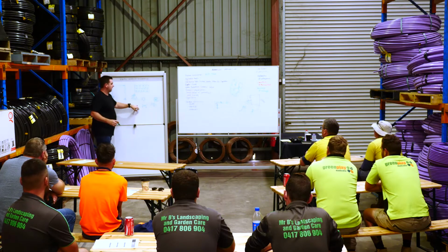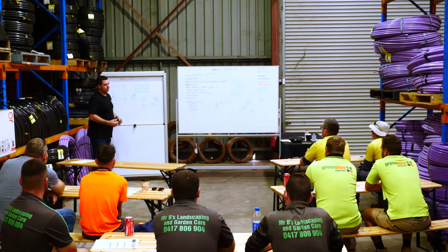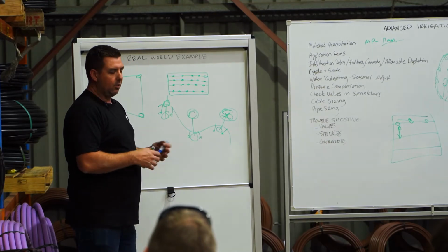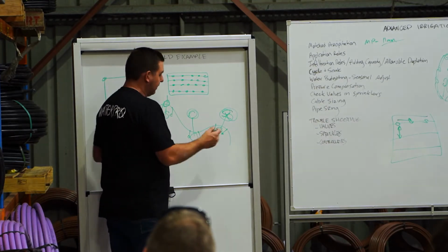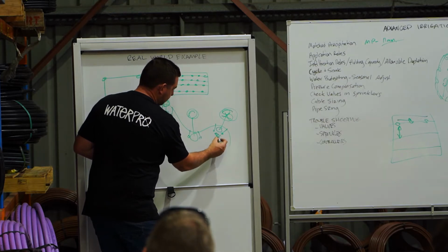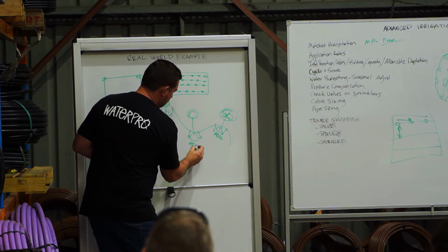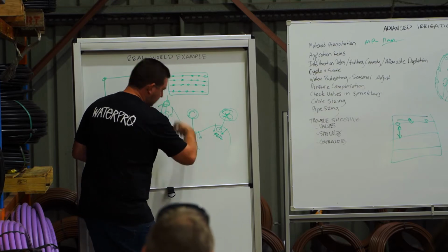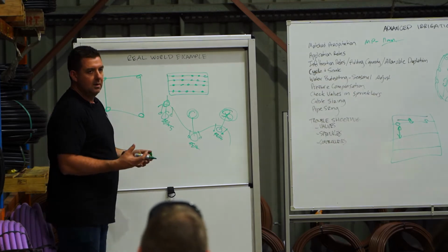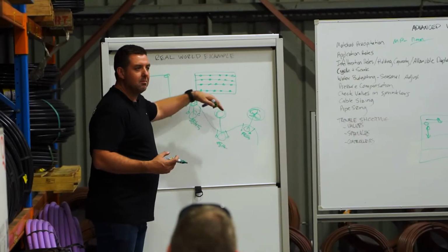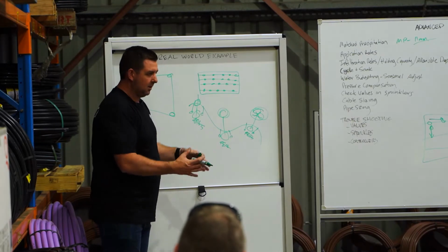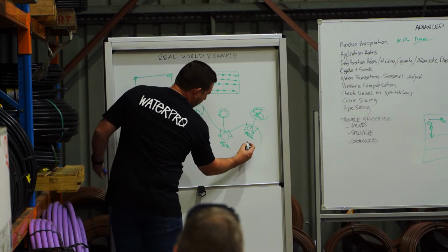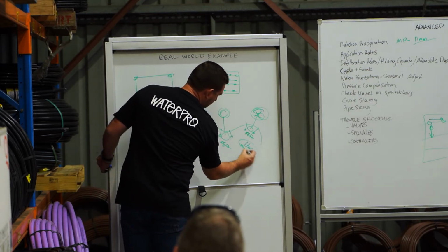And then you might think we've got large pots. We're going to put shrubblers. You guys have used shrubblers. So pressure compensating shrubblers, they do 24 litres per hour each. So you might be getting 48 litres here, here, here. In this situation, we're going to water for an amount of time because you could work out how many mil you're putting out, but it doesn't really mean anything because it's not over an actual area. So we might say we want to water that for 1 hour a week